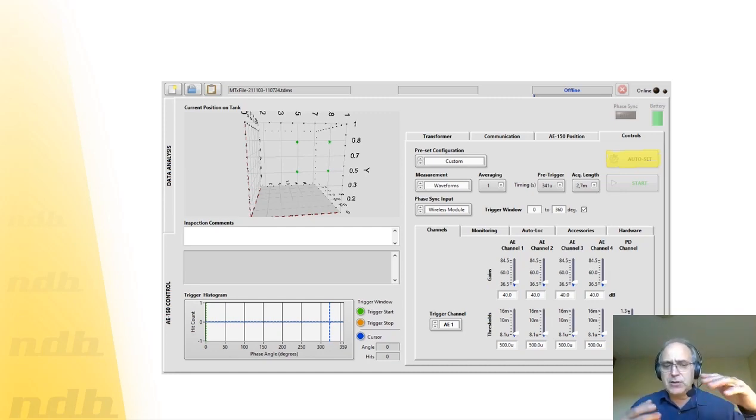As you press auto setting, the unit will crank the gain in order to hear acoustic, but not all the way to saturate it. It sets the gain to a limit where you don't get saturation and you have enough gain to listen to the acoustic. And this is mandatory.